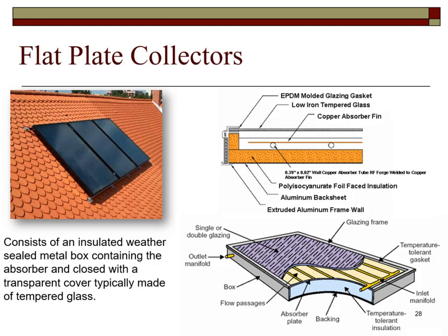The collector should always be installed with the inlet manifold on the bottom, which will allow the cold water to utilize the convection principle learned earlier and thus rise through the system while gaining as much thermal energy as possible. If the cold water were to be introduced at the top of the manifold position, it would also be acted upon by gravity, which would cause it not to spend as much time inside the pipe as needed, thus missing out on picking up as much of the available energy as possible.